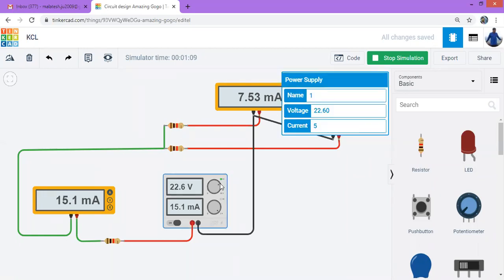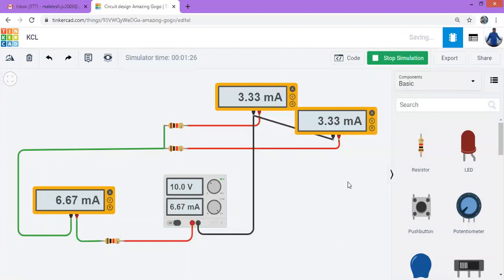Okay, if you want to set a particular voltage for the RPS, if you rotate this, it won't be exactly like 2 volts, 4 volts, 6 volts like this. So it may vary, either more or less. So I want to set this for 10 volts. Just click on this RPS and go to the voltage range, remove it and type 10. So it is 10 volts.